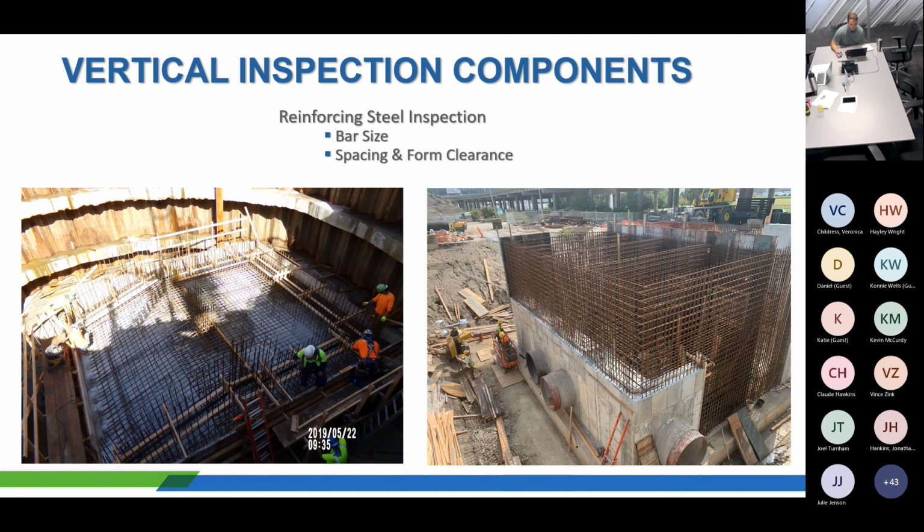And getting out there and really taking a look at what the contractors have put in place. Checking bar size, checking lap lengths, checking tie connections, checking forms. May vary based off of where the concrete is placed on the project.